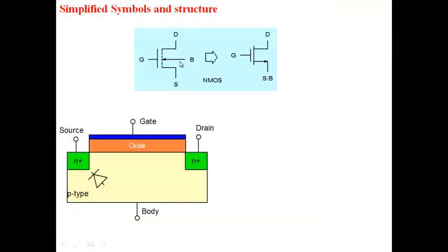All right. So basically the body is P-type and the source is N-type here, or the channel is N-type here. If you look at the PN junction, the arrow is pointing into this particular layer. The dotted line indicates that it's an enhancement mode transistor: when you don't apply any gate voltage, you don't really have a channel. You have to apply a voltage larger than the threshold voltage to create a channel here. That's why the dotted line is there, and the arrow, of course, denotes this, and you have drain, source, and body here.